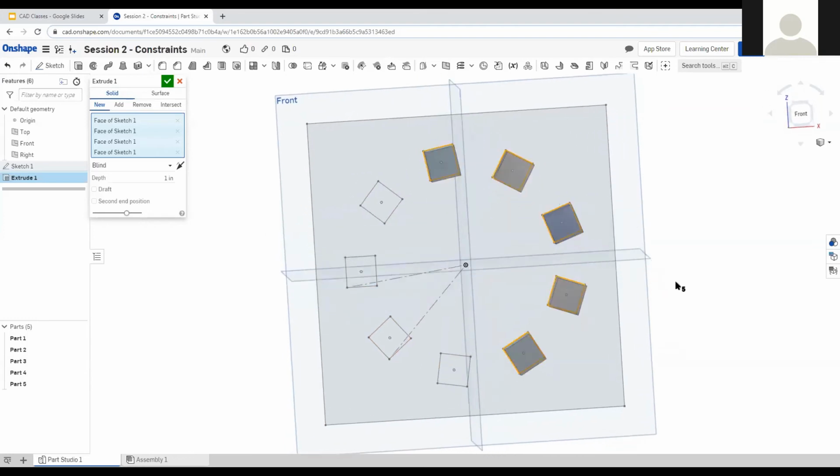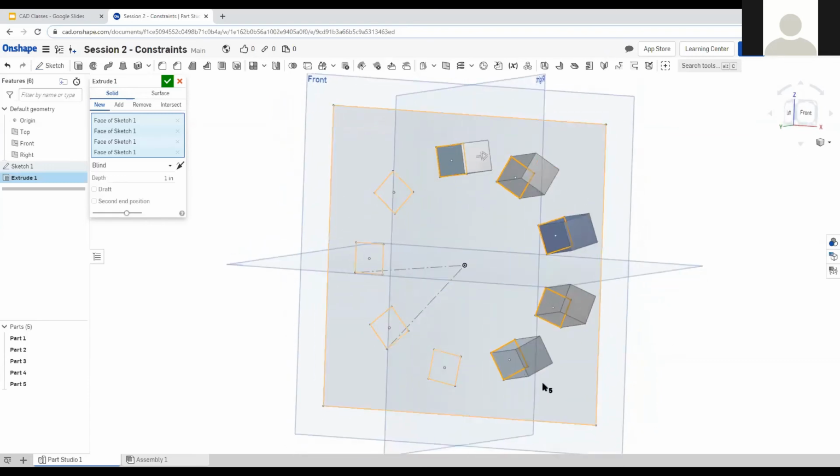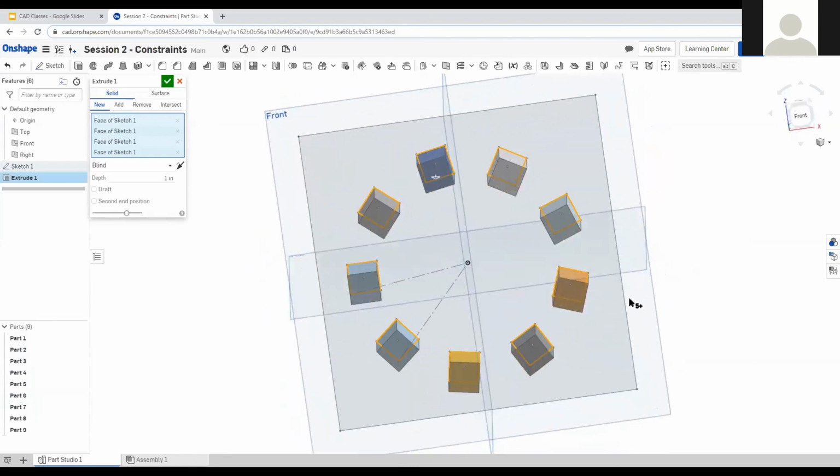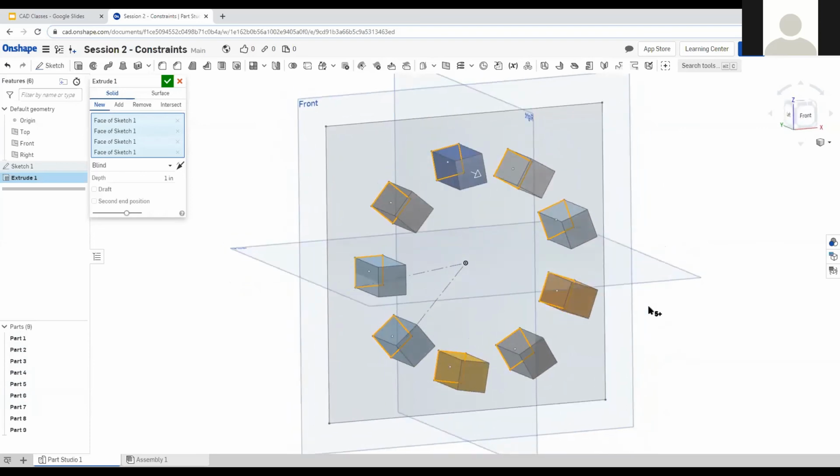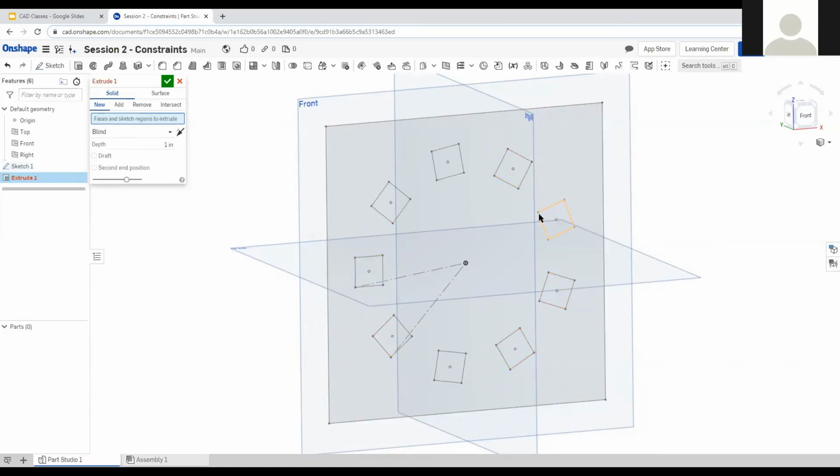So here, since you're trying to create multiple different areas, it's like, oh well, these aren't attached, so it's clearly not the same part. I am going to be smart and I am going to create a part for each one. So at the bottom left of the screen, you can see that it's starting to create a part for each one. If I keep selecting more, it'll keep creating more parts. So I have 7 now. And yeah, if I really want, I could just create a bunch of parts. But most of the time you probably don't want that to be happening. Or if you do, I don't know. I'm sure there's plenty of perfectly valid examples for this, honestly. But anyway, I don't want to have 7 or 9 different parts. I think I put 9.